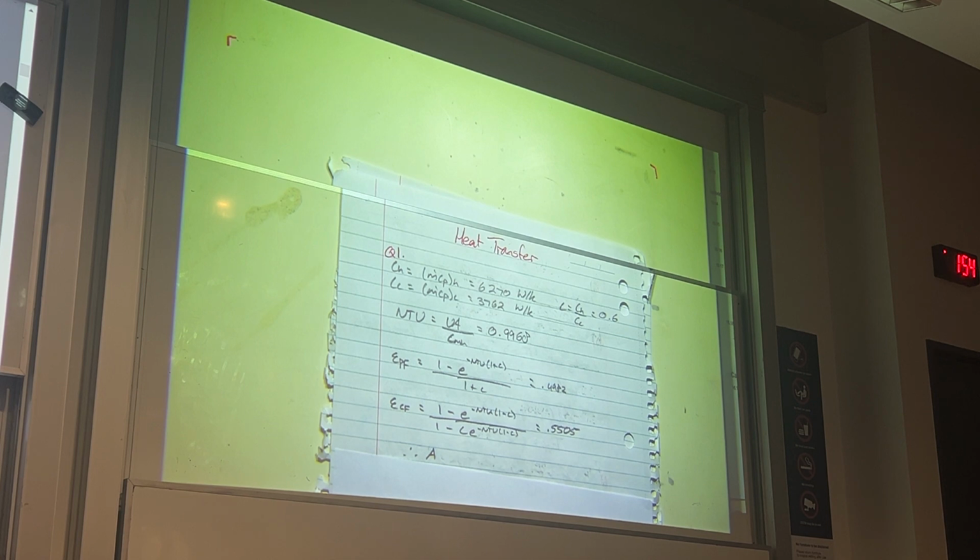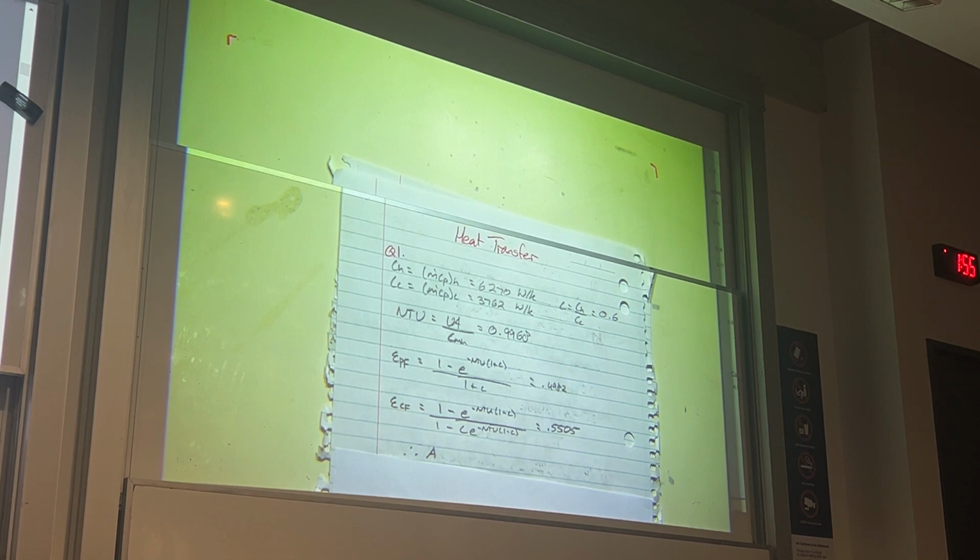Does anyone want to yell out what natural convection is? It's through density changes due to temperature variations. Yep. So natural convection is just related to buoyancy forces. Our air naturally has a temperature gradient, and depending on the temperature, density changes, which affects your buoyancy forces. So very slowly the air circulates.